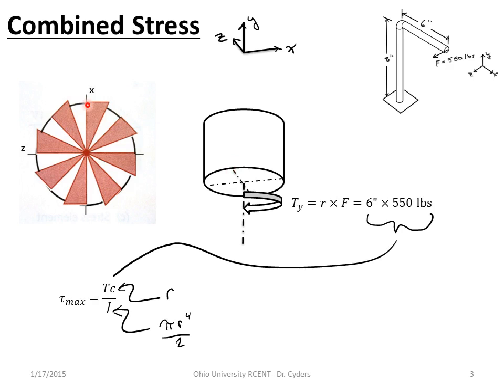If I look at the torsional stress where this cross-section crosses the x-axis, so this point right here, which, if I recall correctly, is point B, the shear stress planes involved are different than at point A, here where we cross the z-axis. Remember always that the torsional shear stress includes the two axes that are not the radial axis.